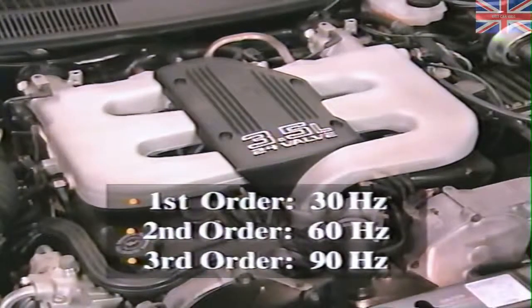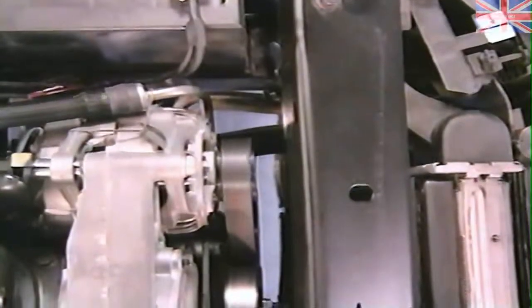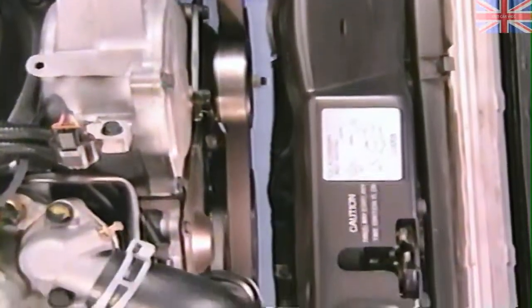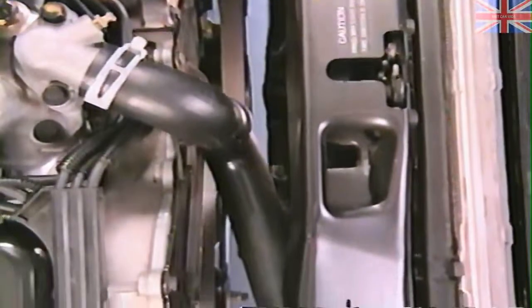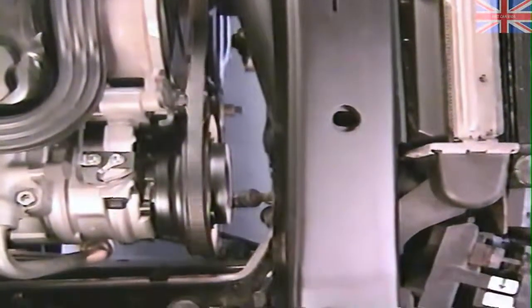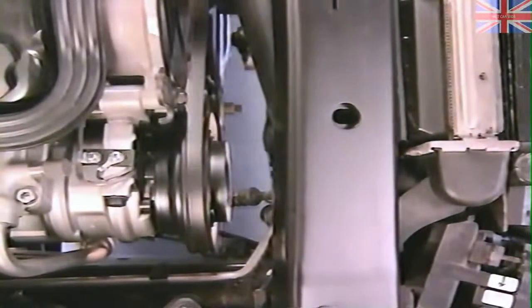You can take this another step and isolate accessory components. Belt-driven engine accessories often produce vibrations at frequencies that differ from the engine's frequency. Why? Because the drive ratios created by the different size pulleys cause the accessories to rotate at different speeds. The accessory frequencies are determined by calculating the size ratio between the accessory pulley and the crankshaft pulley.